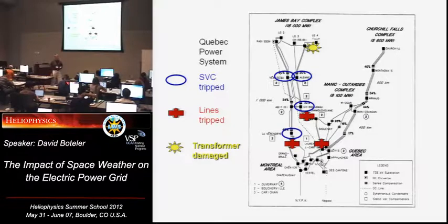There's concern in China. I've got a PhD student from China who's working with me for a year. And a lot of interest over there because they might not have as large magnetic variations as we do in North America, but they go into much higher voltage electric power systems. So they've got an extensive 750 kV network, and they go into a 1,000,000 volt system soon. And so that's going to have lower resistance lines, so they're going to see larger GIC. And then look at what the earth structure is in different parts of the country.